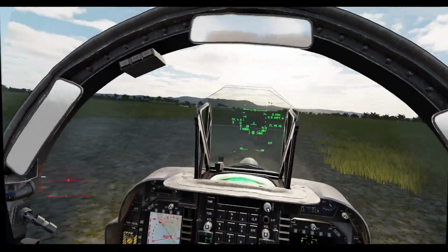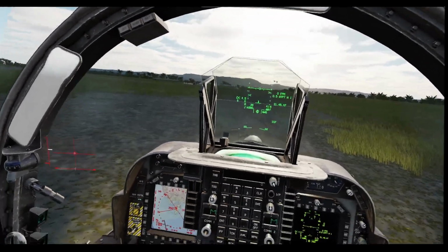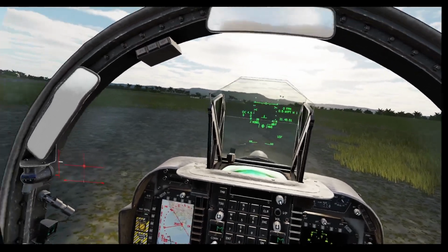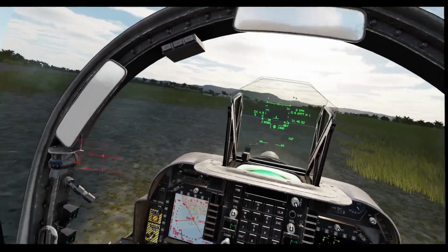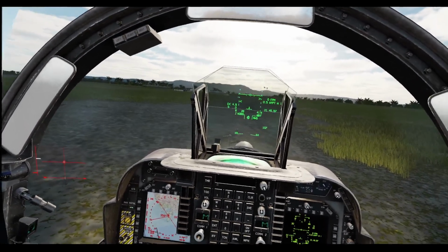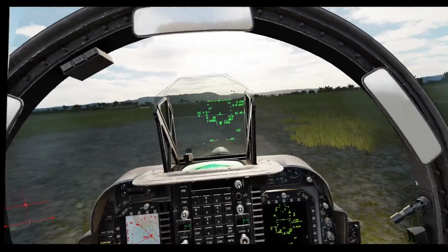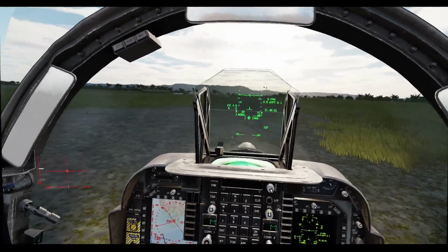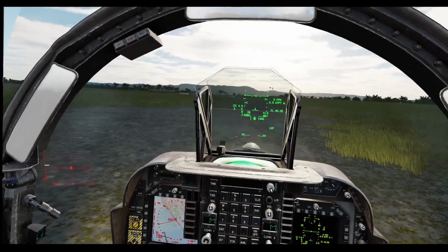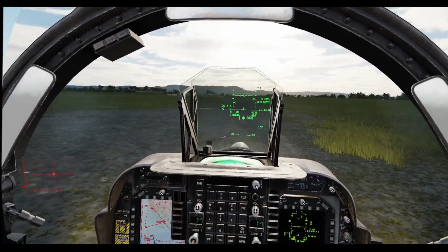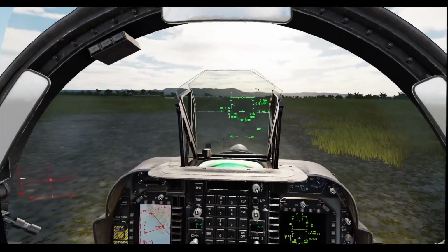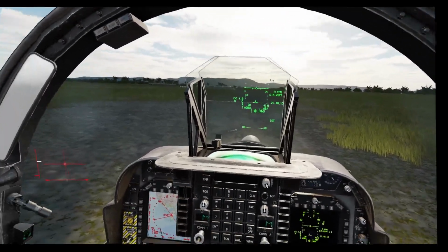And then, of course, remember where the crosswind's coming from, because as you come in to touchdown, you might find that the wind's actually blowing you right to left, or left to right in this case. The wind was blown right to left. So I've rolled out with my nose pointing a little bit right of the runway, which might feel a little bit contradictory at first. You may also find that in order to meet your airway and your checkpoint altitudes, your gates, you might find that the nose seems to be pretty aggressively down.